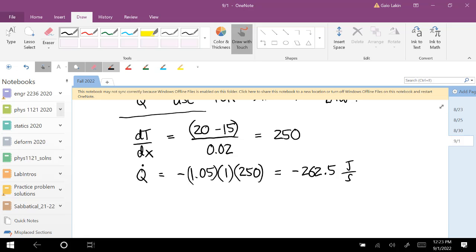Well, heat transfer from conduction always goes from a high temperature to a low temperature. So this just says that Q dot is in the opposite of the x direction. Heat is transferring in the direction of negative x. You can think about that sign convention, or it's just as easy to think about what direction the heat is going to transfer. It's always going to go from high temperature to low temperature, because that sign doesn't help you in the differential form of the first law anyway.